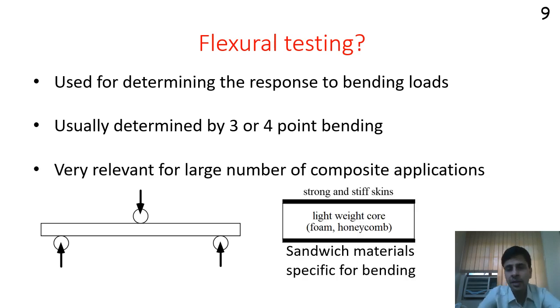Now this is very relevant for a large number of composite applications. In fact, there is a family of composite material which is designed specifically to take bending loads. For example, in our last theory class in classroom, we learned about sandwich materials. These sandwich materials are exclusively used when my material is expected to be subjected to bending loads. So flexural testing is very, very important.